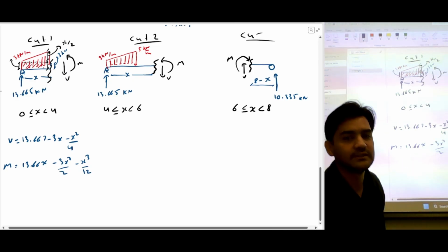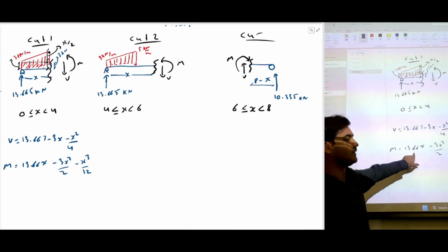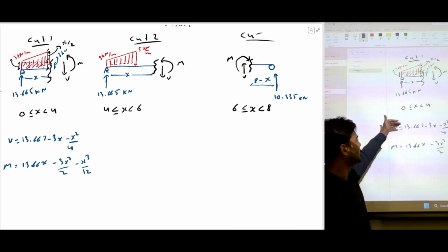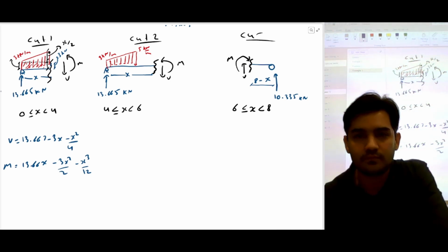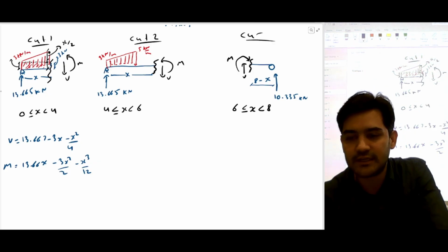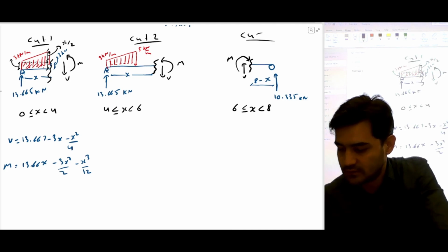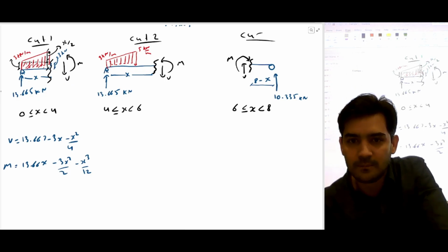And you can also see there's a relationship. If you integrate this, you're going to get this value, and if you do the differentiation of this, you're going to get this value. So basically, moment is an integration of shear force. We can try to solve for this also. I'm just going to write the final answer for cut 2, but I guess cut 2 is straightforward.